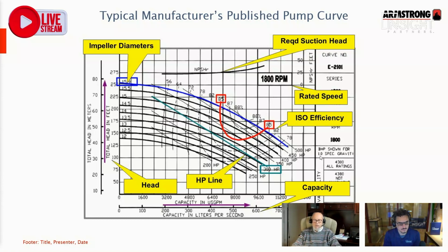Understand that stuff is basically an oil, kind of a mineral oil based product. So specific gravity and density play into that as well. If you get one of those applications, reach out to the guys at Insight Partners and they'll work with us, and we'll get the right pump selection for you. Sometimes we have to bump horsepowers to make it work.